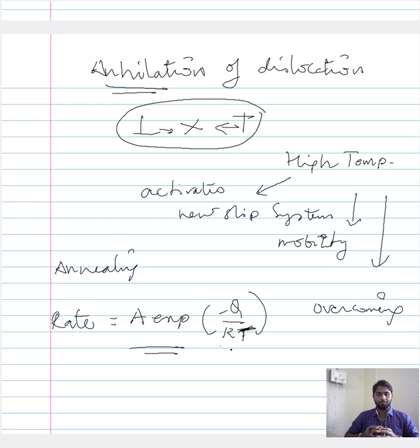So by this, one can reduce the number of dislocations, thereby reducing the energy. And also, ultimately for our purpose, when you reduce the number of dislocations, the new dislocations that are being formed are easy to move. That means the plastic deformation becomes more pronounced. We saw that during the transient period, the plastic deformation was restricted because the increase in dislocation densities impeded each other, and therefore impeded the overall plastic deformation.